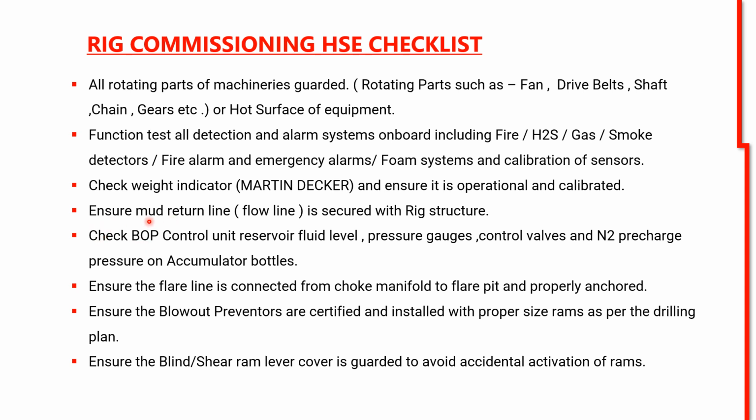Ensure mud return line, flow line is secured with the rig structure. Check BOP control unit, reservoir fluid level, pressure gauges, control valves, and N2 pre-charge pressure on accumulator bottles. Ensure the flare line is connected from choke manifold to flare pit and properly anchored.